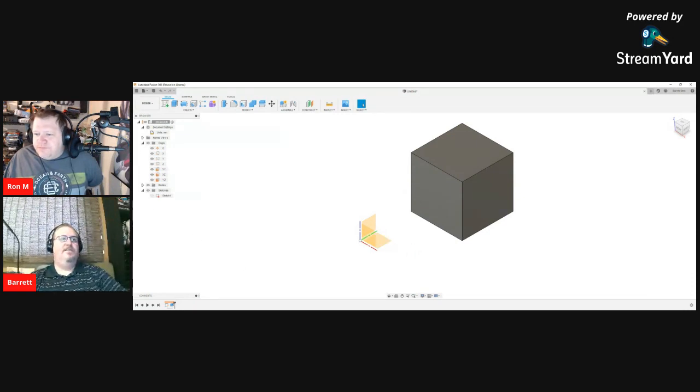Now you notice the sketch disappeared, and that's because we didn't have it selected. There's where the sketch is. If I turn the sketch on, you can see it. So controlling visibility of things can be useful. Most of the time, you don't necessarily want to see the origin. It can get in your way, but there are times when it's useful. If I start a new sketch, the origin becomes visible automatically as I need it, because I might want to start a new image on a sketch.